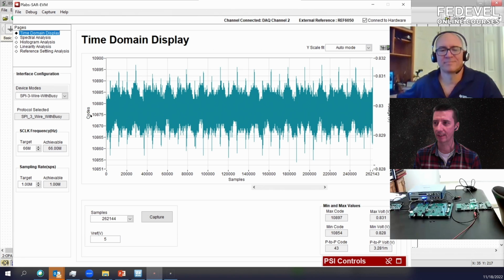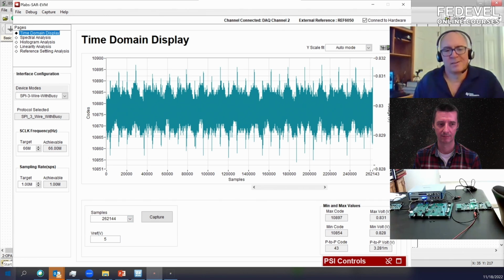Okay, so what can we do with this? How can we remove this noise? Shielded cables, shielding the board itself, or the test design, whatever it is, the test board. Of course, you have a lot of videos on the idea of doing good printed circuit board layout, and anything that's on the printed circuit board, your switching power supplies, your high-speed digital communications. If you don't use good PC board practices, you'll not only cause maybe data integrity issues where you get communications errors, but you'll very often get problems with pickup of that digital signal into your sensitive analog.